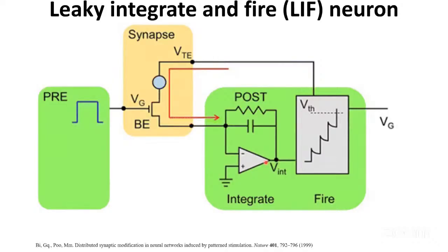So these two together work to perform the computation using the new spiking neural networks. So this model is called the leaky integrate and fire model, where we are using a capacitor to mimic the membrane potential, and then we use a leaky integrator to perform the integration, and then moving toward the resting potential.